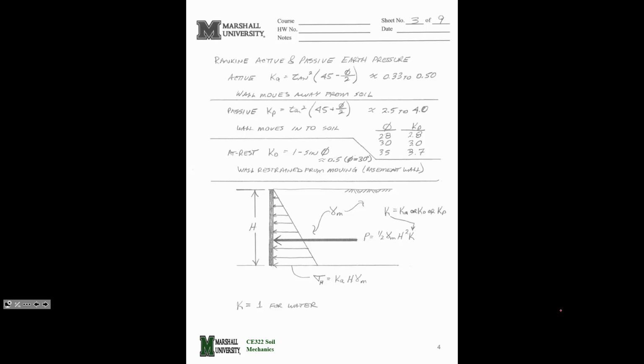There's definitely, guarantee you 100% there's going to be some kind of earth pressure questions. Definitely going to be something like that. Rankine, and it seems like all the example problems I've ever seen, they pick on Rankine's methodology. Looking at the active or the passive earth pressures. You got to remember if we're looking at K sub A, the active state, there's a negative here. If you got K sub P, you got a plus here. It's the only difference. So P and plus.